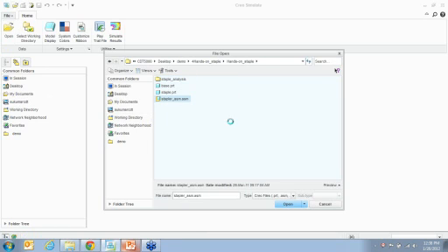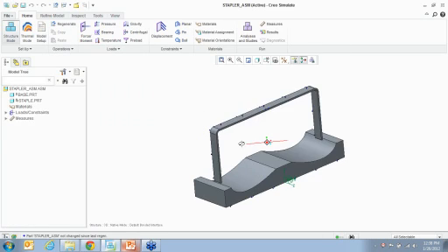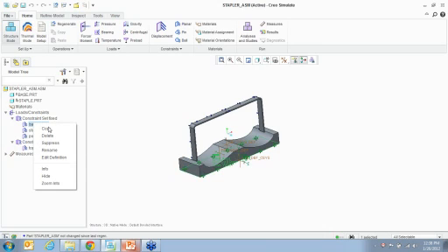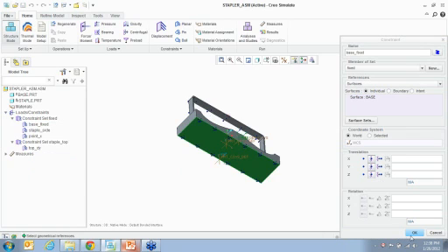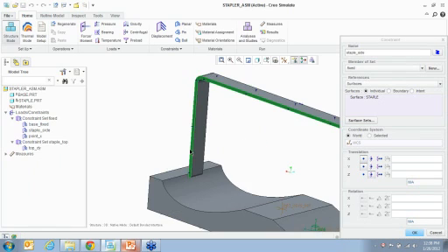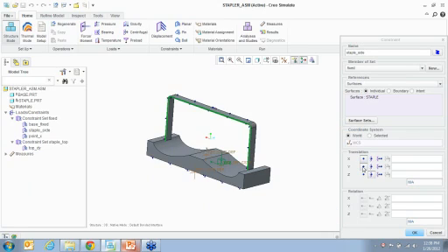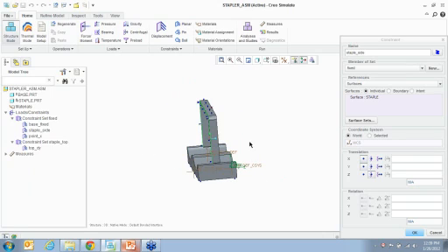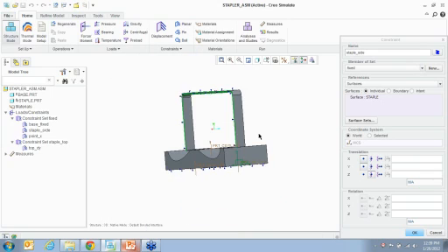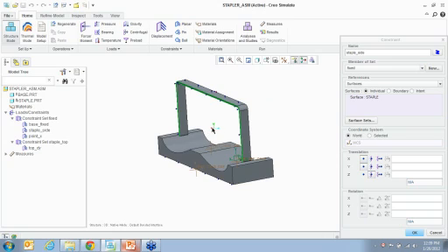So we have a stapler assembly. All right. So I want you to see right now I have a few loads and a few constraints. So I'm going to go base fixed. You can see that I've fully fixed the base of it. Okay. I'm going to pick the side of this stapler and say I can only translate in the X and Y, and I'm fixed in the Z. The Z direction is this way. You can see which way the Z is right here. So it can only go up or down, right? But it cannot go this way.